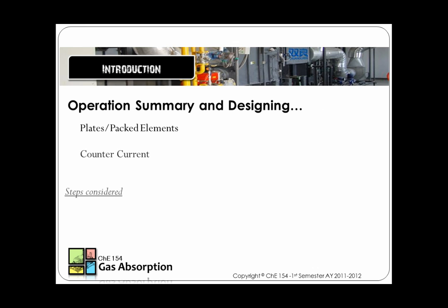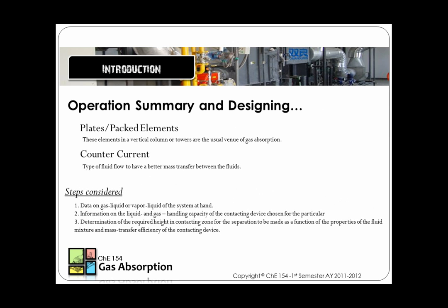In designing, we have to consider the following. First, the plates or packed elements, which are the usual venue of gas absorption. Second, the countercurrent flow, which gives us better mass transfer between the fluids. Also, we have to take note of the data on gas-liquid or vapor-liquid equilibrium of the system at hand, information on the liquid and gas handling capacity of the contacting device chosen for the particular operation, and determination of the required height in the contacting zone for the separation to be made as a function of the properties of the fluid mixture and mass transfer efficiency of the contacting device.